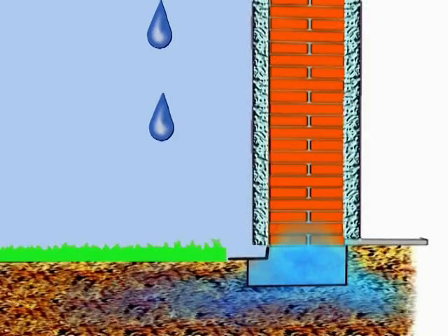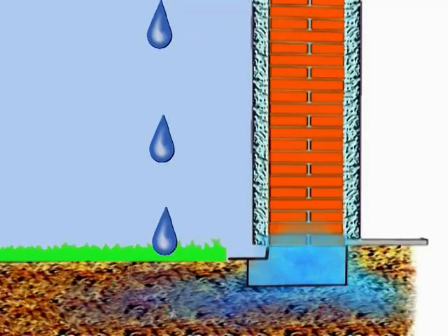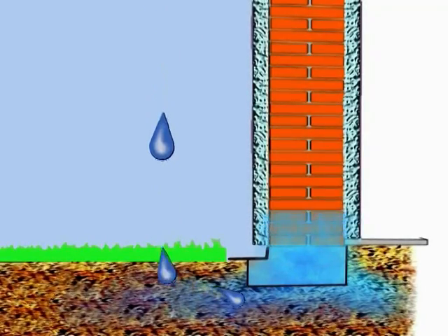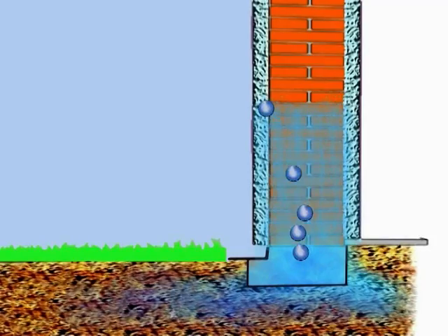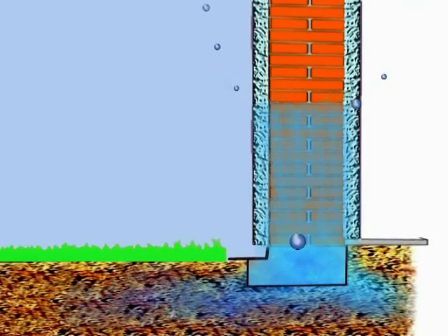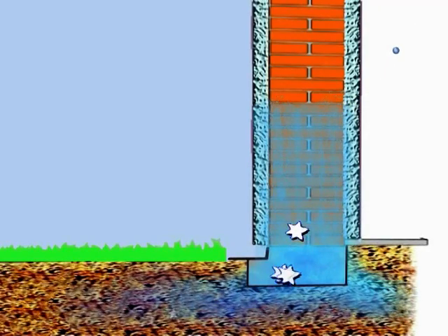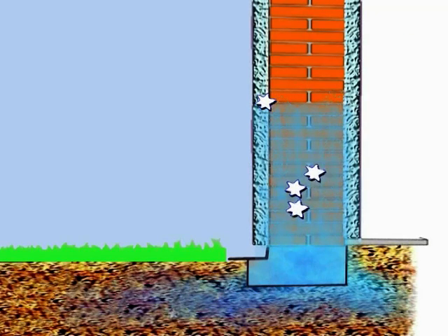Moisture penetrates the ground due to precipitation, dew or groundwater. It then enters the foundation of masonry where it rises and evaporates, mainly in higher portions of the wall. The greater the quantity of moisture, the larger is the amount of evaporation at the evaporation zone. As a result, salts that damage the basic structure of a building enter the masonry from the ground.